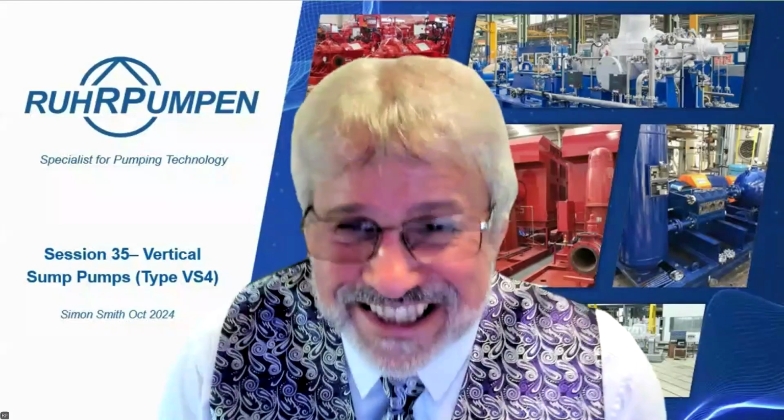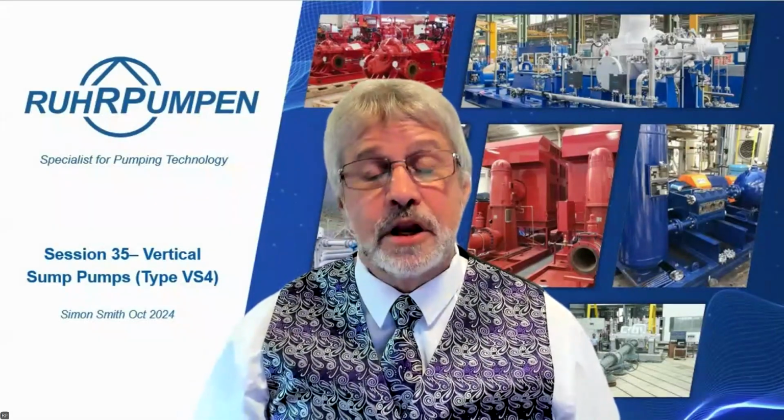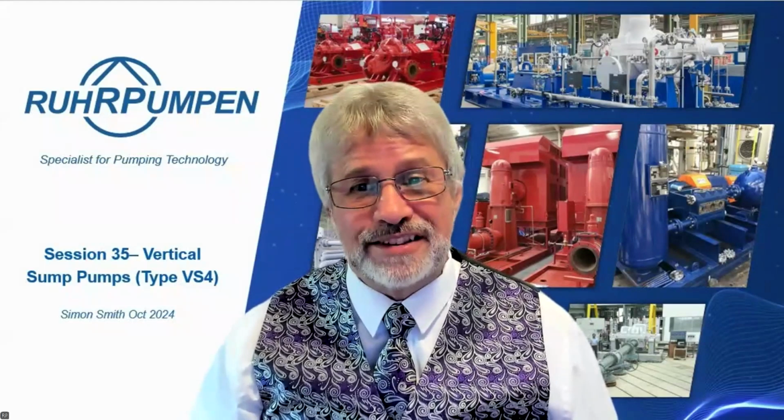Mayuresh Patel says, can lateral analysis be performed for the vertical pump? One of the pump vendors informed me that lateral analysis is not significant for the vertical pump. Is it true? Yes and no. Yes, he's right for a standard product like this, the VSP and the VSP Chem. It's a pre-engineered product. We've already done the analyses and we've built them dozens of times. We know that they're not going to hit a natural frequency, and you're not going to get a critical speed problem.